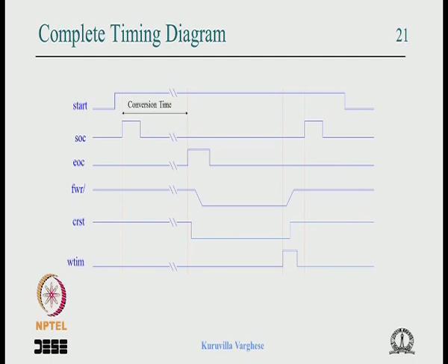So we have come to a good point to derive the control algorithm, and looking at this waveform you can derive it. It is very easy. Let the state machine come to a starting state, and all the output signals are inactive. SOC is 0, FIFO write is 1, reset is 1.